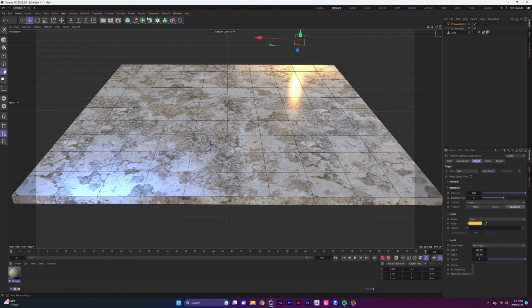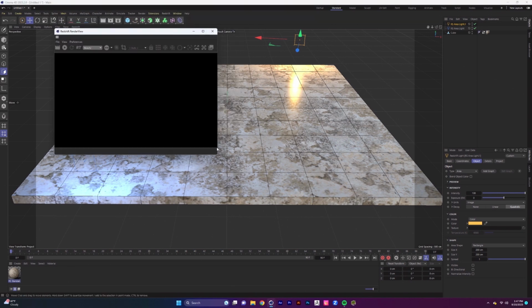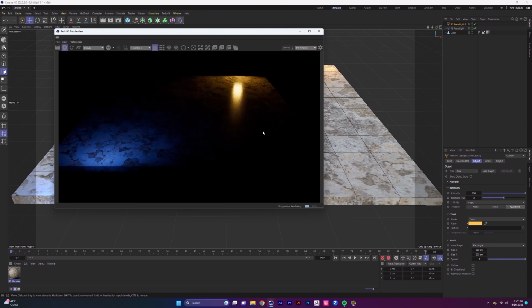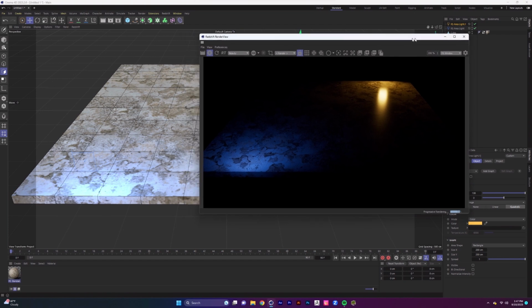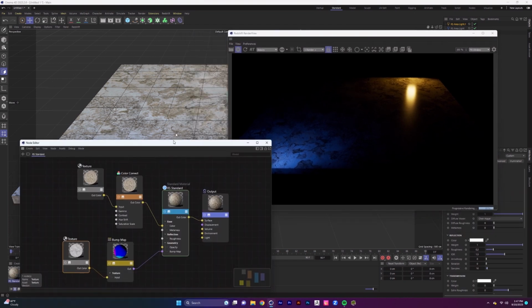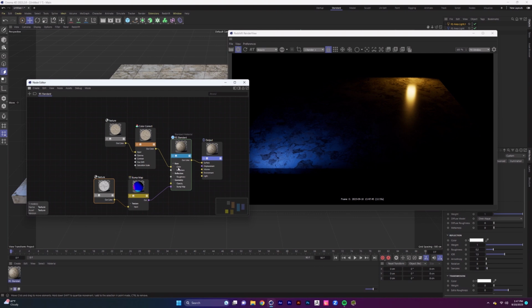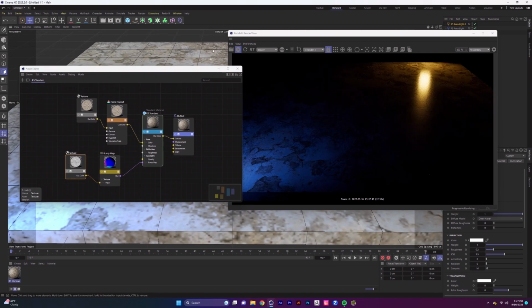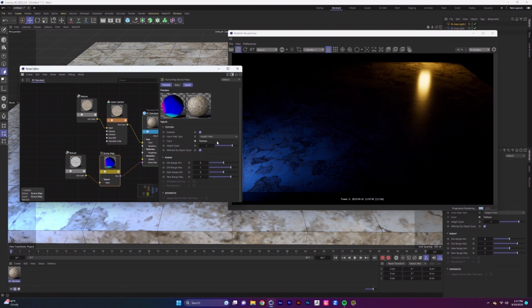Now let's open up the render view and we'll check out what this is looking like. So we'll scale it up. We'll do fit to window, push play. Okay, so we have our texture on, our bump map, which we really can't see yet. So let's bring out the detail. Let's select our bump map node and we'll set the height scale to 3. We're starting to see a little bit of something. There we go, 20. And we see some protrusion happening.